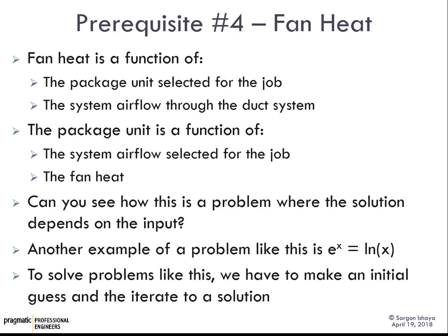I'm going to move on to the fan heat. So here we have a circular problem. The fan heat is a function of the package unit that you select and the airflow. The package unit that you select is a function of the airflow and the fan heat. So do you see how we have a circular problem here?